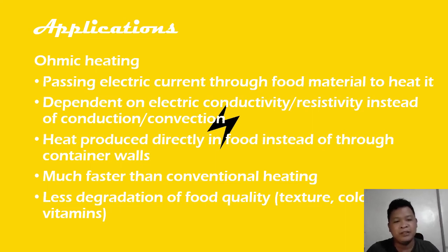So, and because you are treating the food material as an electrical conductor, then the rate of heating would depend on, among other things, the electrical conductivity or resistivity of the material instead of your typical conduction or convection.